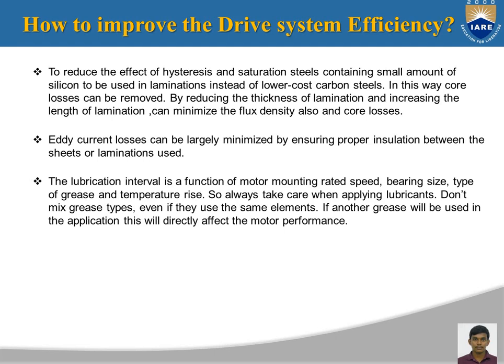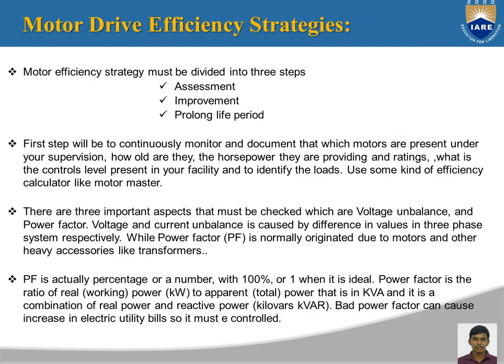Eddy current losses can be largely minimized by ensuring proper insulation between the sheets of the lamination used. And the final thing is that we have to use a proper lubricant so that there is no friction and no heat production when the motor runs.